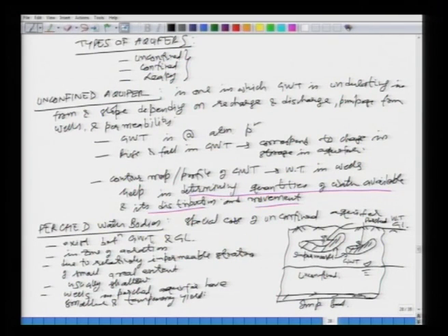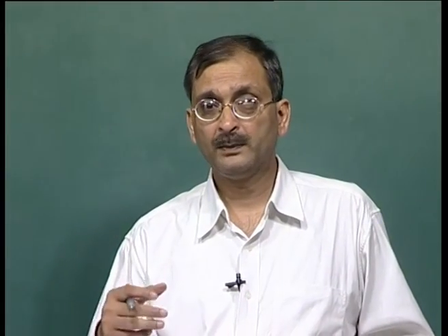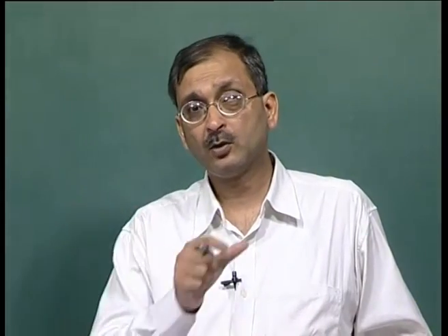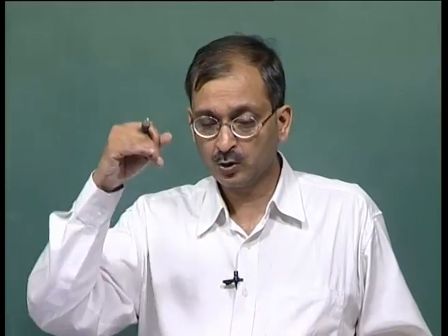Sometimes what happens is we start digging a pumping well and we encounter some water. We feel that we have reached the groundwater table, and we start pumping the water out. But after a few months, or after some time, there is no water, because this was a perched water body and not the actual groundwater table. If you dig deeper, it is very difficult to go through that clay strata. That is when we realize. So, whenever we are doing any investigation for water, we have to go sufficiently deep.